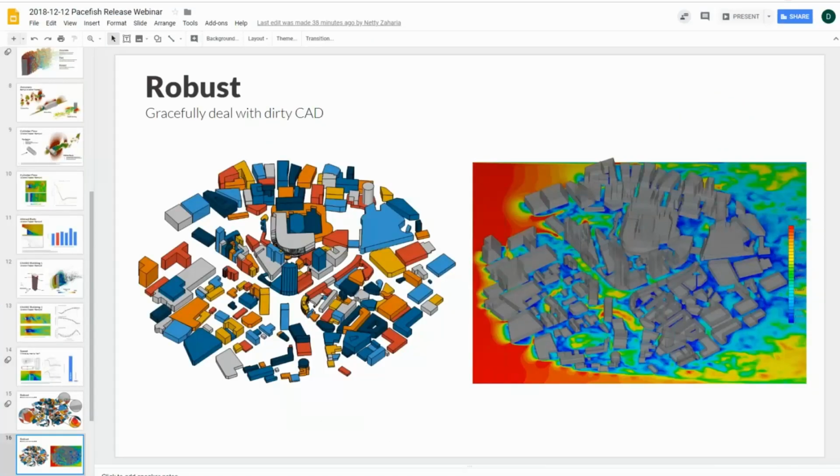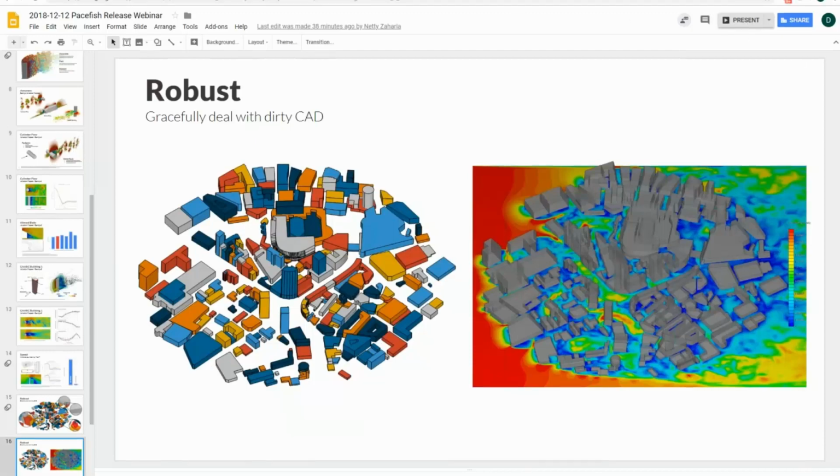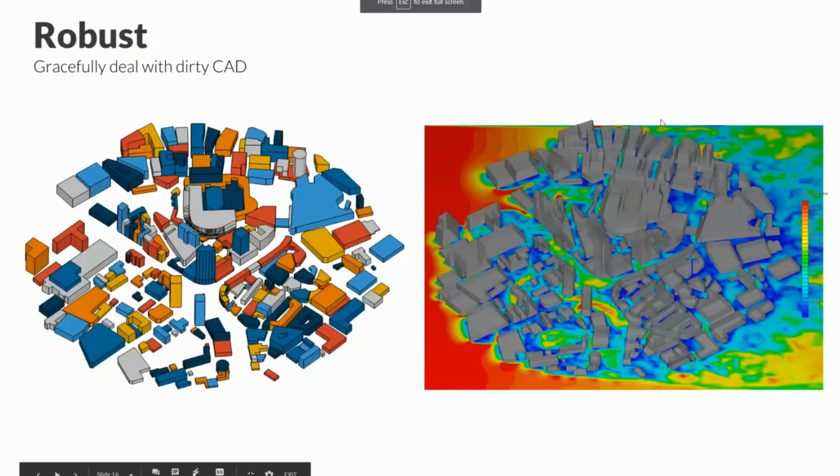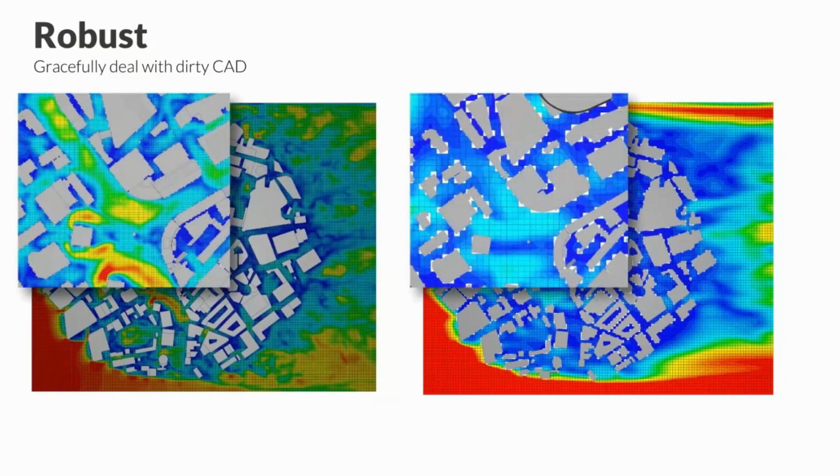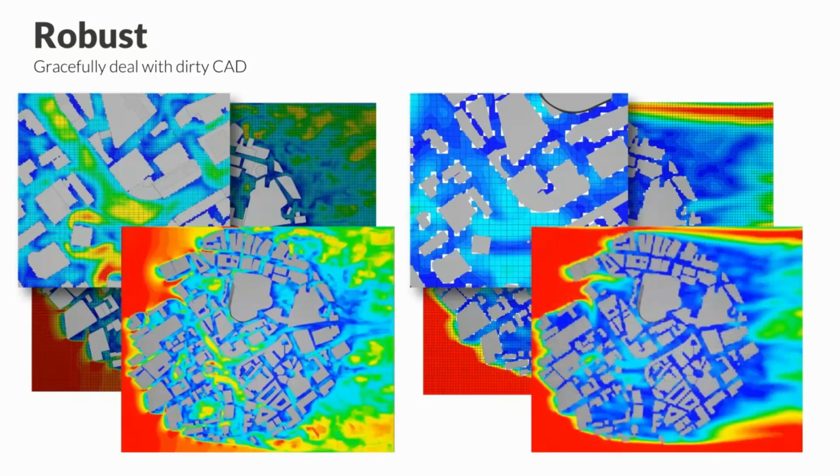And I think I have a slide for this as well, showing this side by side. Yeah, there you go. This is what we just looked at. On the right, a coarse lattice, on the left, a finer one. Zooming into interesting regions, we can see that this specific area in the middle of that city plan is much finer resolved on the left. On the right, I have some artificial blockage because I don't resolve the flow channel finely enough.